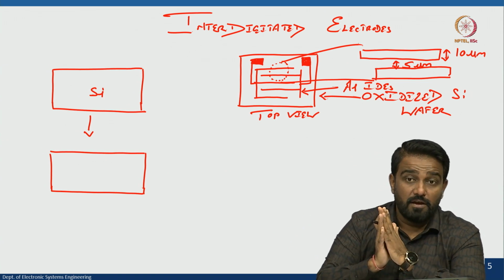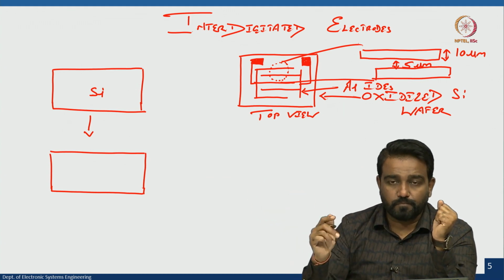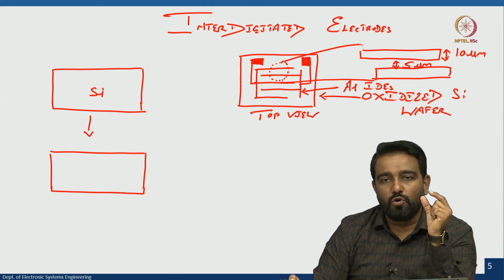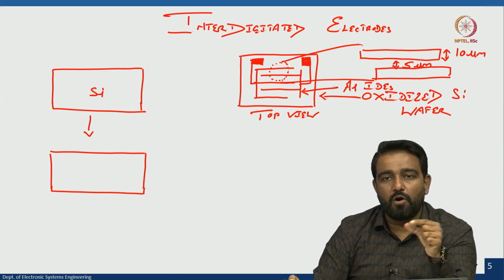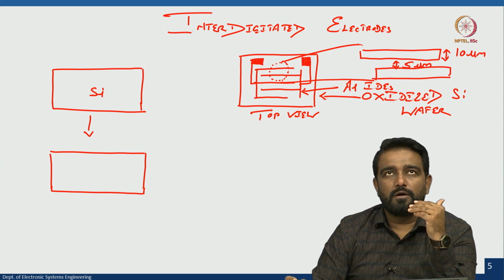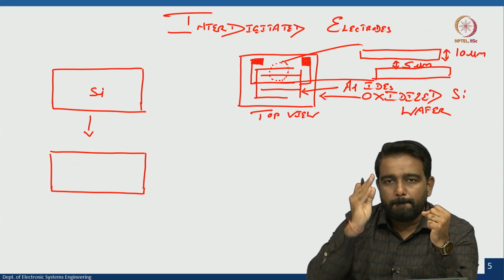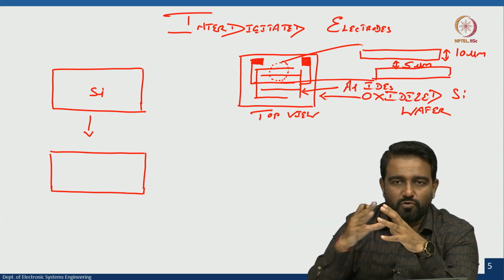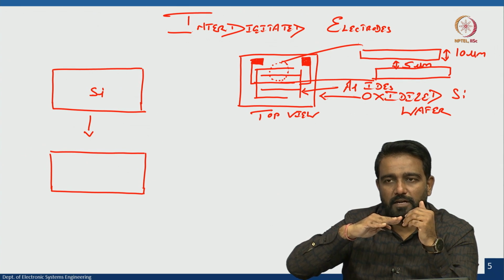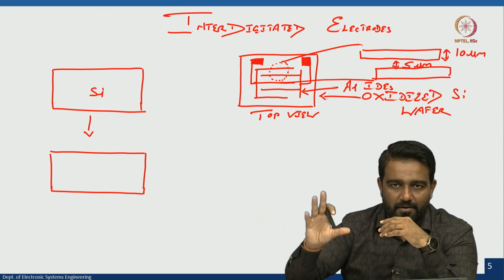So, the next process is we will perform thermal oxidation. Thermal oxidation is a technique by which we grow silicon dioxide on silicon, all right. It is a furnace, and in the furnace you can load many wafers, close to 25 wafers, and initially the temperature is raised to 900 to 1200 degrees centigrade, in that range.